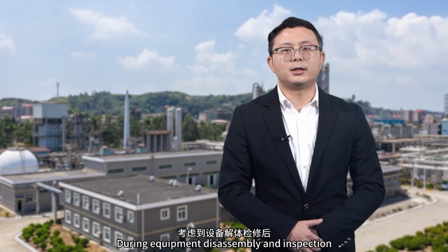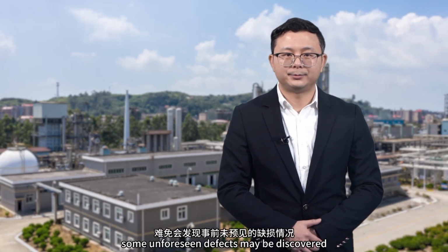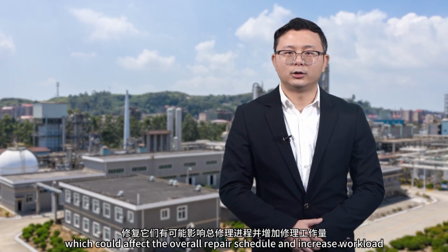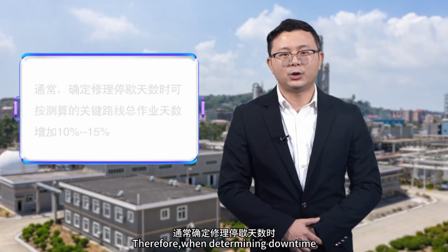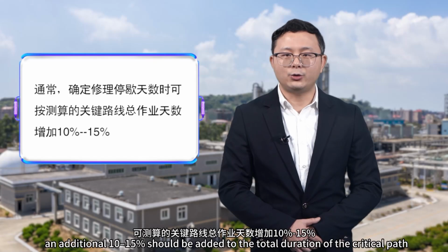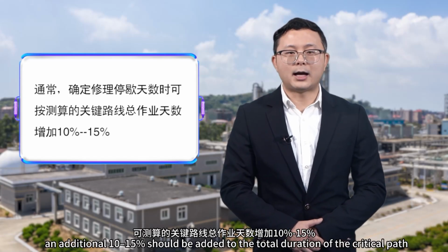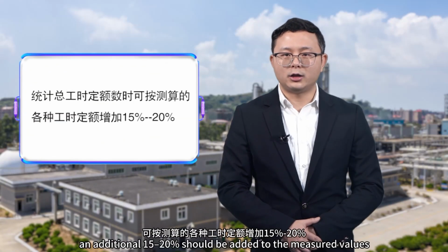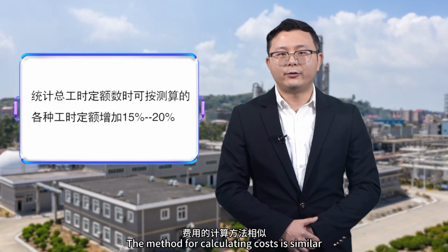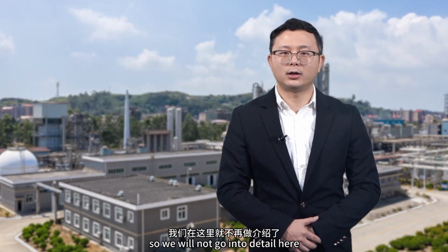During equipment disassembly and inspection, some unforeseen defects may be discovered, which could affect the overall repair schedule and increase workload. Therefore, when determining downtime, an additional 10 to 15% should be added to the total duration of the critical path. When calculating total man-hour norms, an additional 15–20% should be added to the measured values. The method for calculating costs is similar, so we will not go into detail here.